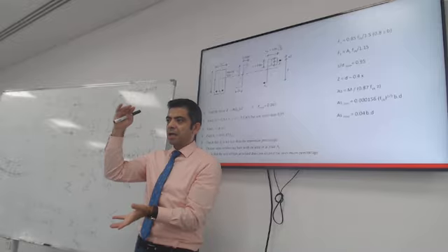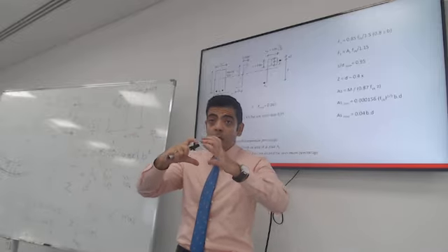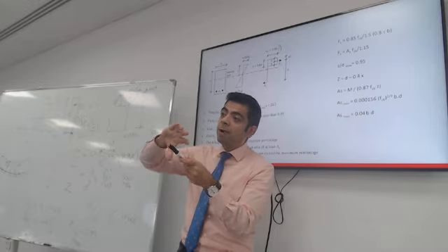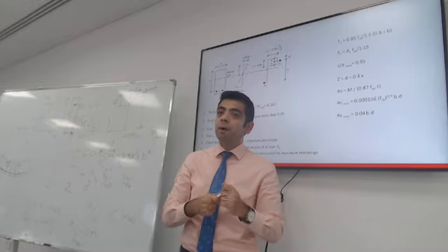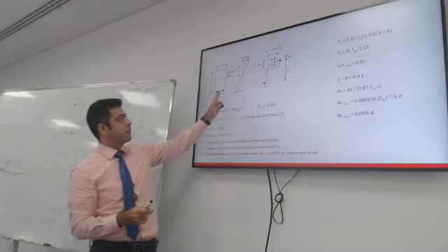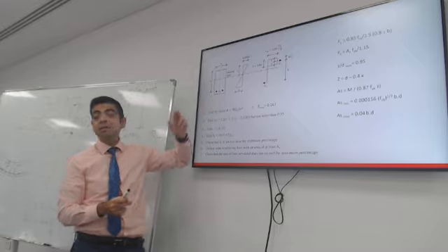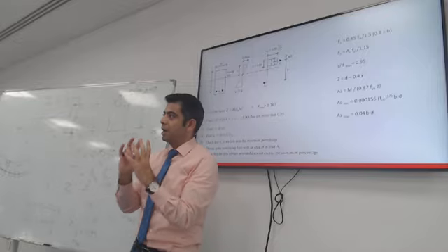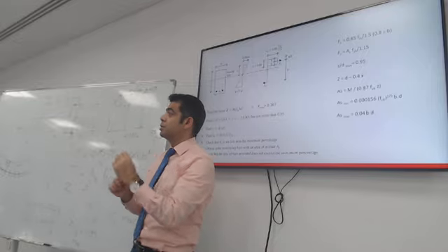If you put too much rebar in the beam, there will be no space for concrete to envelop each bar properly, which takes us to the last check: make sure the spacing between the bars lets the concrete flow around them and create bond with each bar.